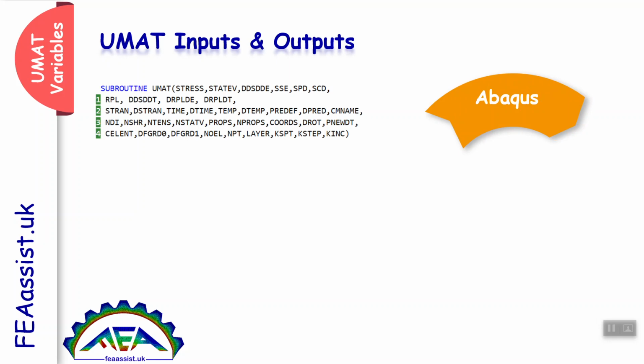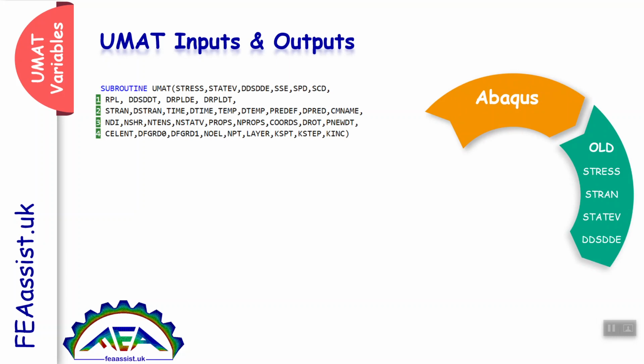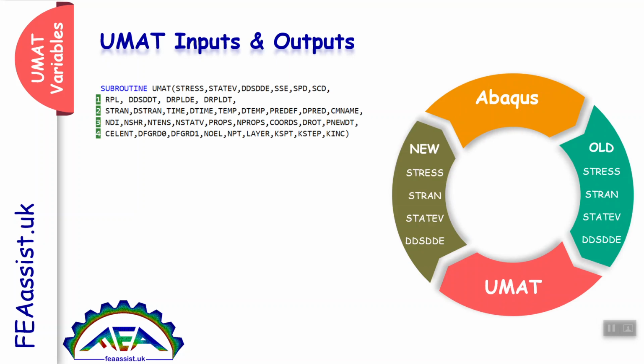Actually, all these variables are computed in Abaqus and transferred to the UMAT. In the UMAT, we need to write equations based on our constitutive behavior to recompute all these variables and return them back to Abaqus. This is how Abaqus and UMAT interact with each other, which is necessary to write a well-working UMAT.